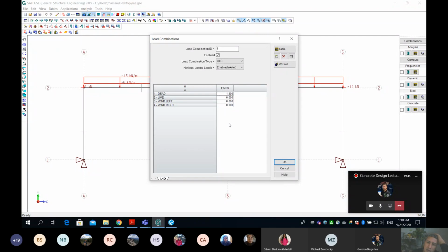We have to do more than that. You can see here there are some controls on the top right. I will go through some of them. For example, this one is very intuitive. If you don't like a load combination, you simply click on the bottom left key here and then hit delete. And if you want to create more than one, you can see this button, it says add a new tab.